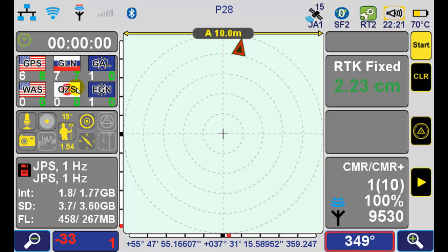Below satellites block is the summary setup block, which shows we have programmed to record voice and record picture, and here that we are expecting only centimeter level RTK solutions. The gray box in here shows that we have programmed not to record spectrum data. We have programmed 15 degrees of elevation mask.